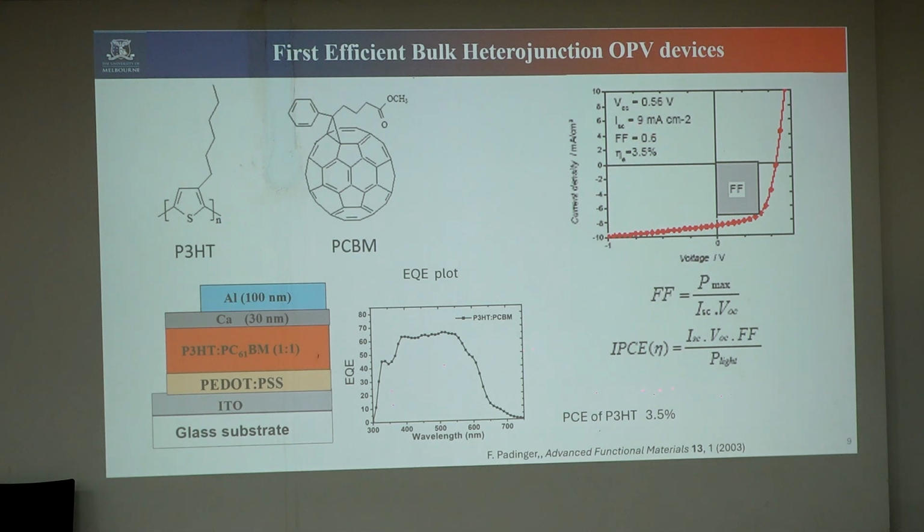3.5. EQE is another factor that tells you that, ideally, if we give one photon into the device, we want to get one electron out. If that were the case, we would get 100% efficiency. No device in the world will reach 100% efficiency. There will be a lot of recombination and a lot of loss. That's why even for silicon the best efficiency is only 25.6%. One photon, one electron out means 100%, but we only get a fraction out. The remaining is recombined, which is waste charge.